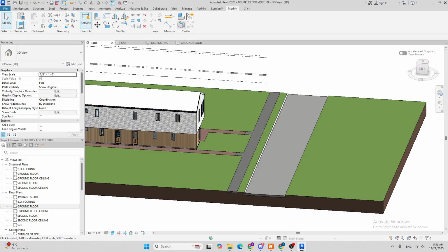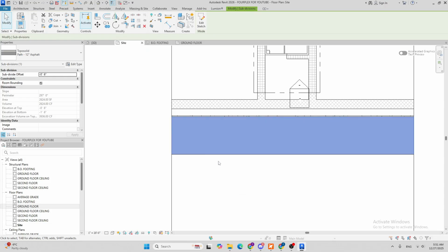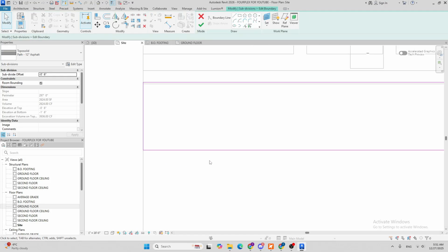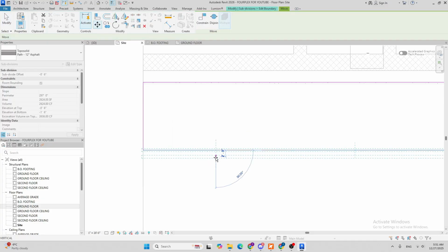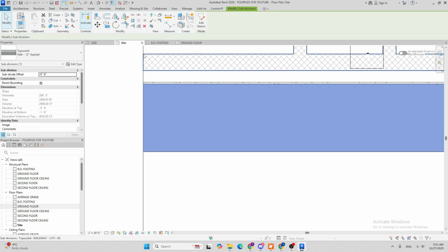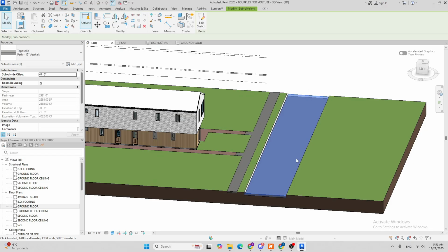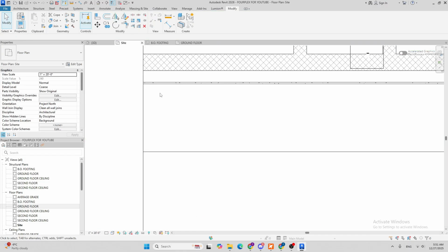So I'm gonna do that. What I'm gonna do is probably I'm gonna go to the site plan. I'm gonna click the driveway. I'm gonna click edit sketch. Click this one, and I'm gonna click move. So move in 6 inches. So the total street dimension will be 20 foot. My bad. So go 3D, check it out. Yep, that's fine. Go site plan.